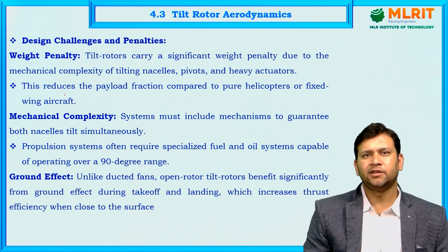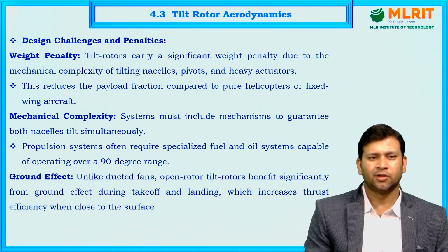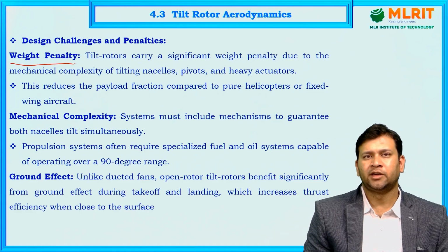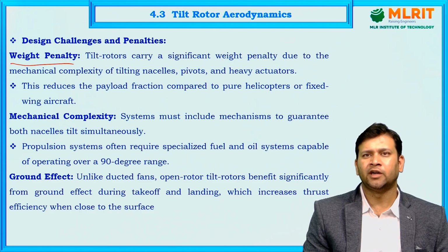The design challenges and penalties which a designer will face in tilt rotor aerodynamic configuration. The very first one is weight penalty, as tilt rotors carry a significant weight penalty due to the mechanical complexity of tilting nacelles, pivots and heavy actuators, which reduces the payload fraction compared to pure helicopters or fixed wing aircraft.